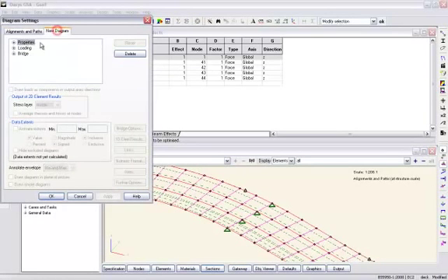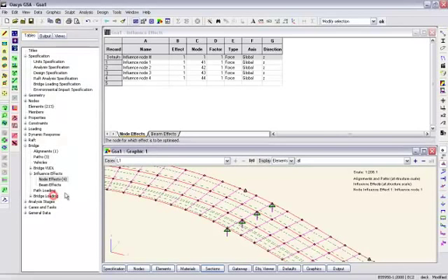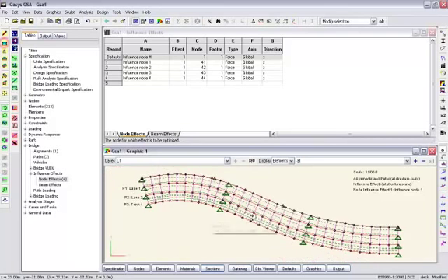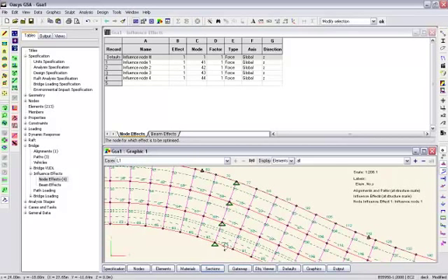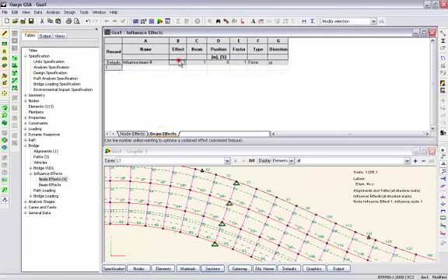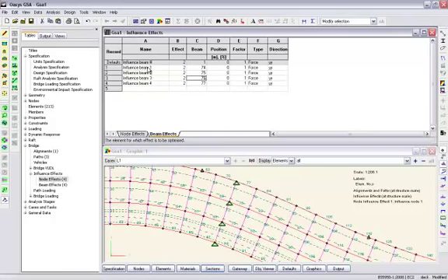We add in a new diagram, which is our influence effects, and you can see there's the support point. So we're going to be optimizing our loads to maximize the reactions at this point. Similarly, I want to maximize the loading for the moment at this point, target moment. So let me switch on my beam elements, 74 to 77. So it's beam. I'm going to change the grouping to 2. Beam 74, 75, 76, and 77.